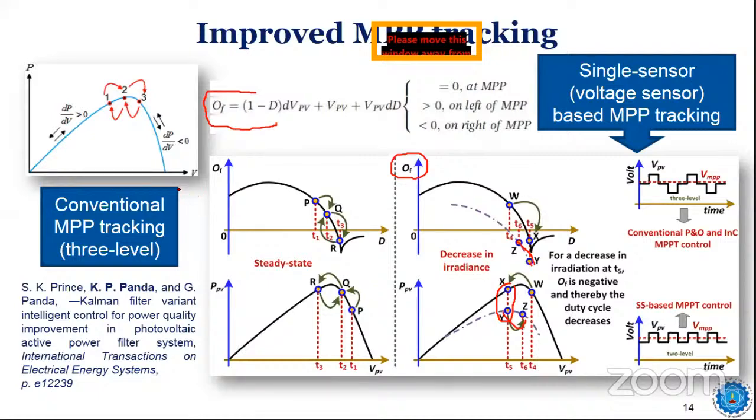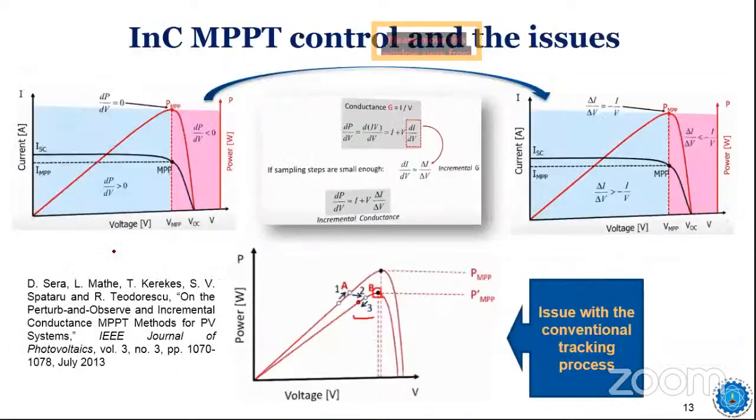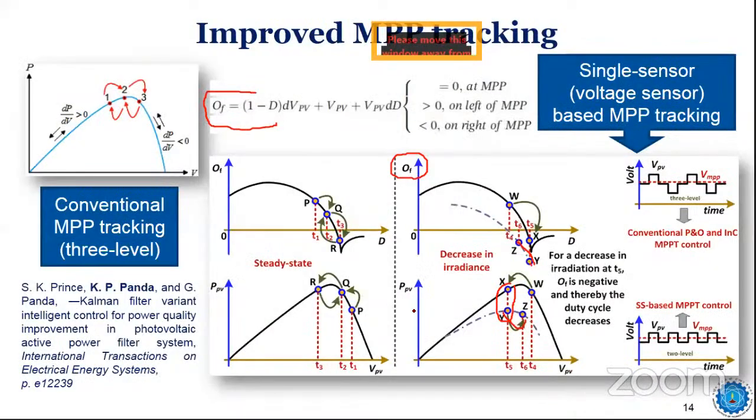The value of duty cycle initially set here needs to be adaptive type, okay? Because if you take a fixed perturbation, the result may not be optimum or may not be good. If you take an adaptive type perturbation, you will see the results are more interesting or better, or the oscillations are less. So that is how the research is going on.